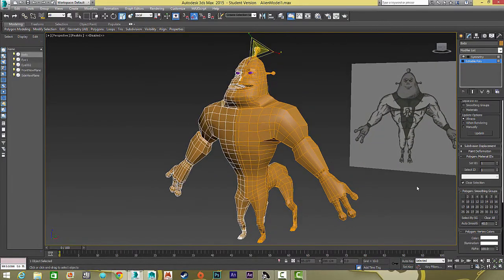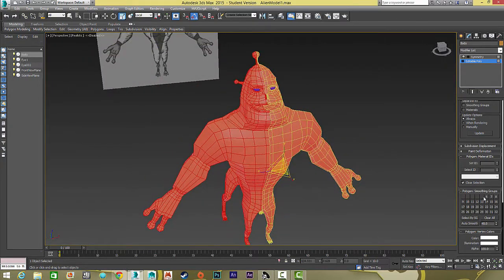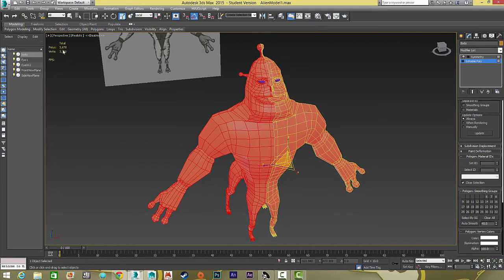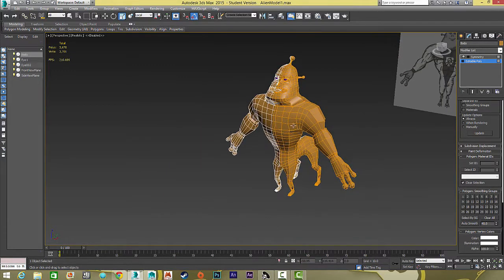So what I'm going to do is, we have a lot of different smoothing groups on everything. So if you drag select everything, we have 5 different smoothing groups. Now there's 32 different options, so we literally don't need to use all of them. You can probably still stick within the first 5, and that's a good kind of goal to do. Don't use as many as possible. We use as little as possible, because it is saving out different information or more information. So we're trying to reduce the amount of polygons, or information, that we actually do need. So we have a low amount of polygons that will work well in the game, and there's many more we can add to get more smoothness around the arms or other areas in the face. We also want to save on the data with the smoothing groups, which make things look like it has more geometry there than what it really does.